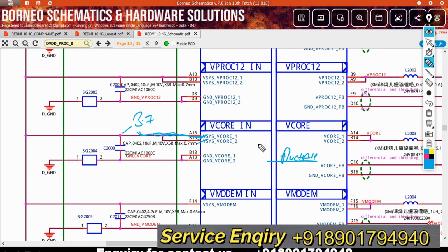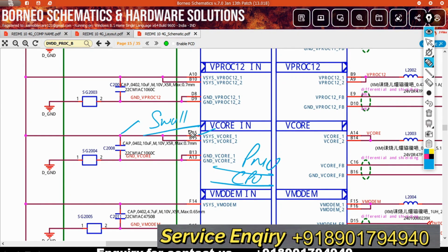This is also a basic work. We always forget our basic things. Most of the time, we do not notice the basic things. We go directly to the CPU and other IC changing processes, but we forget the basic work. If this line is open, from here to here, whatever you do, change the PMU, reball the CPU, this fault will not be repaired on this motherboard, because these small basic things are important. We always run after the difficult one, but we forget about our small things.